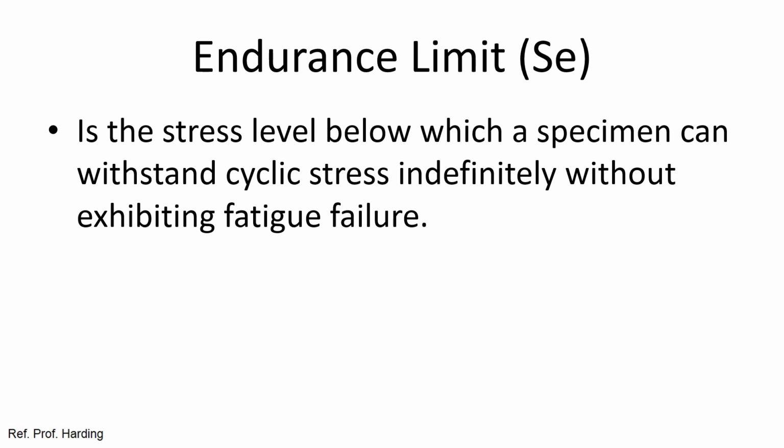The specimen is going to be our implant or our abutment or our post screw, and there's going to be a stress level at which those things are going to fracture, and that's called the endurance level or endurance limit. Stresses above that will result in fracture of the component or implant, and stresses below that level will be withstood indefinitely and your components will not fracture. So this endurance limit is very important to the survival of our osseointegrated restoration.